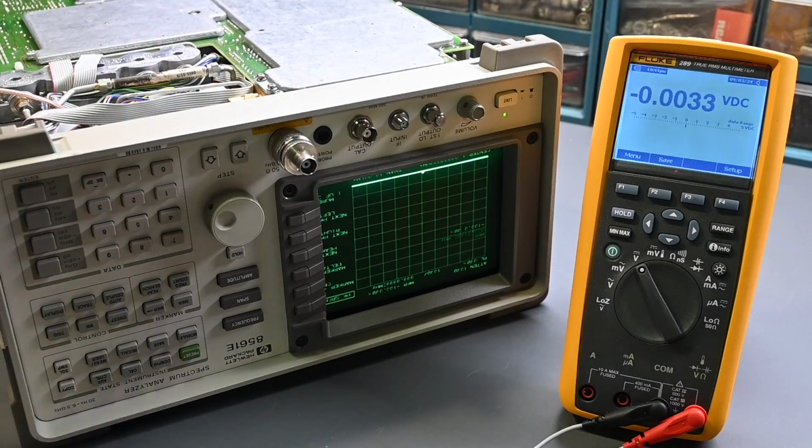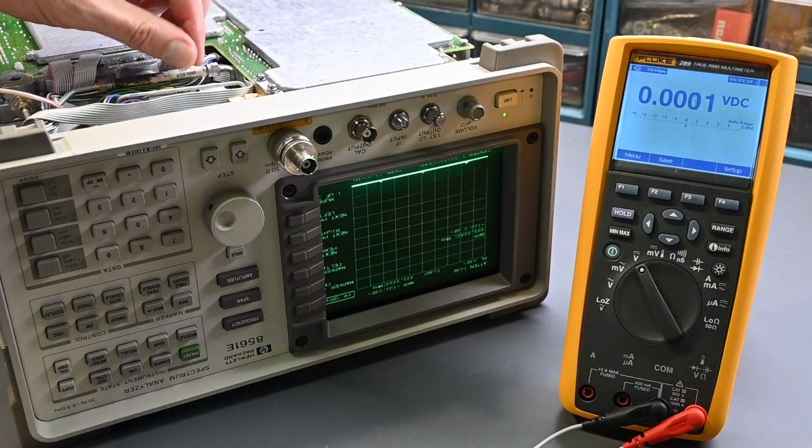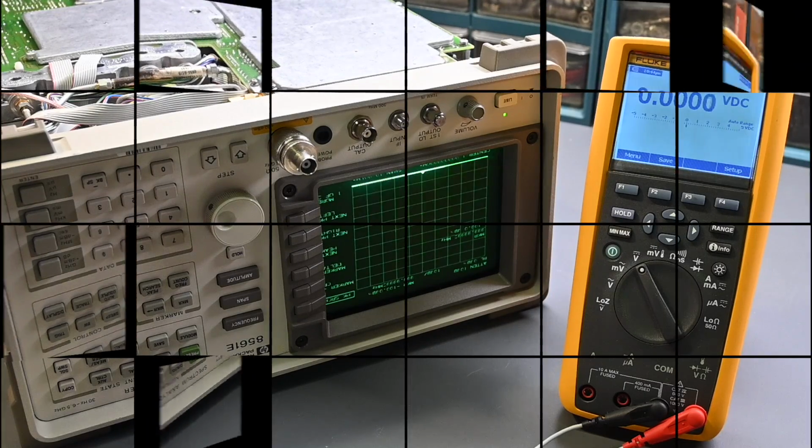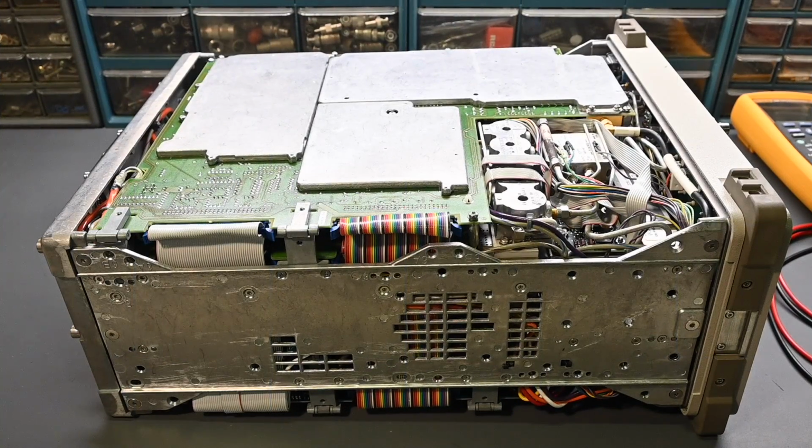So that's the voltage going to the low band switch. So that is correct, and that switch should be turning on and then just passing that RF signal, and it's really not doing that. It's attenuating it, and different frequencies, low frequencies are attenuating more than high frequencies. So I have to think that the switch in YIG tune filter has developed a problem. So with the troubleshooting and testing that I've done on this A10 module, I'm certain that it's defective, specifically the RF switch inside that module.